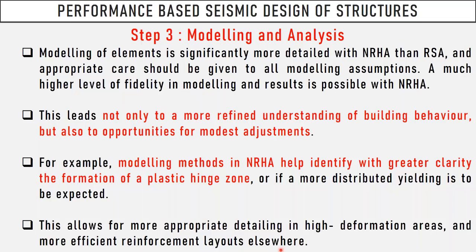And of course, at the end, in order to have a more refined understanding of the building response, you need to make a nonlinear response history analysis, and you evaluate the deformations, like in the plastic hinge zones.